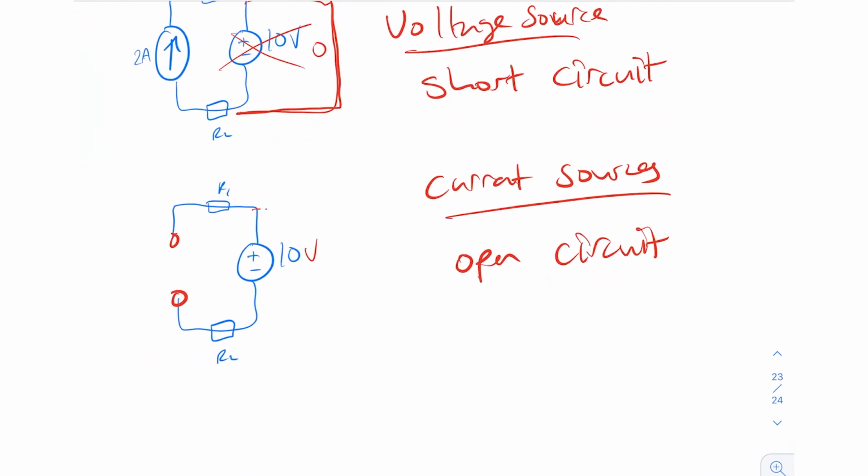And for the opposite, for a current source, its internal resistance is going to be infinity, as high as possible. So in terms of having an infinite resistance, if you had an open circuit, then no electricity can flow through it. Basically, if you had a circuit and then you cut the wire, now between the two pieces of wire is just air, right? So even though air doesn't have an infinite resistance, you basically have an infinite resistance in terms of the electrons inside that wire.